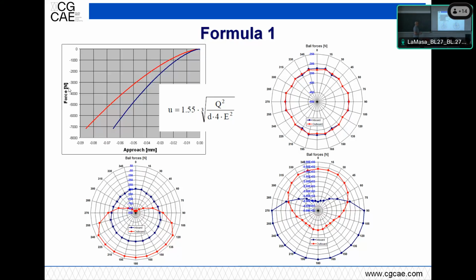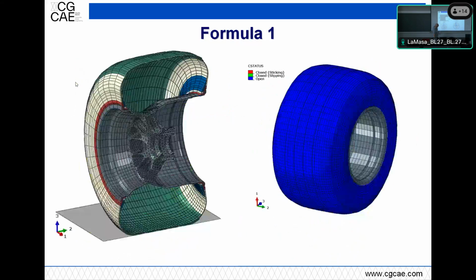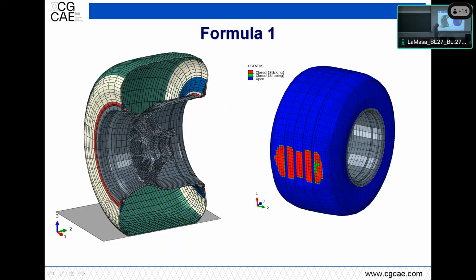And this one as well might have some problems, because there is a curve given by the bearings manufacturer where you have a maximum in terms of life. So if you go too low with the preload, you lose mileage. If you go too high, you lose mileage. So there is a little margin where you can play to try and reduce that, or you can decide to live with what is happening. If the bearing survives, of course.